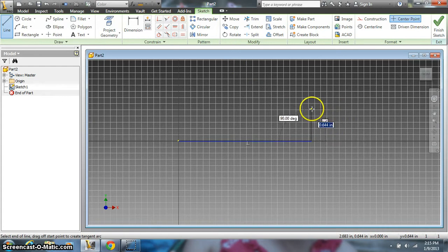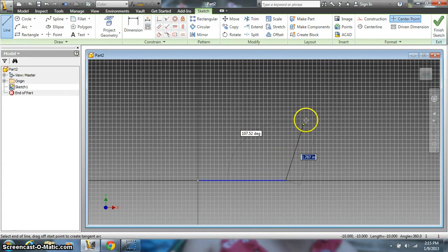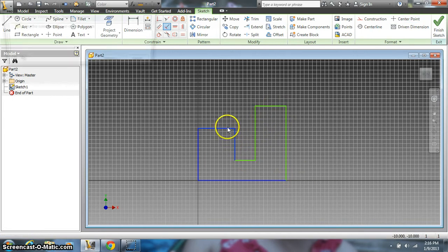It doesn't matter. What I'm going to do right now is zoom out a little more and kind of get a rough idea of a shape I want to have. I know this is my last line, or second to last line. I can go ahead and make this thing perfectly line up right there, lock it on, green line. I know it's a closed shape. There are no openings here, so that's good. Right click, done. Constrain, perpendicular. Double check one more, we're good.